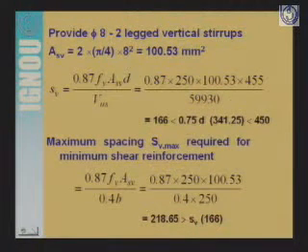So here 0.75 D means 0.75 into effective depth, and this value comes out to be 341.25, which is much higher than the spacing provided, and also our spacing is less than the maximum value of 450 mm specified in the code. Means this value that we are providing is on the safer side. We can provide it very well.